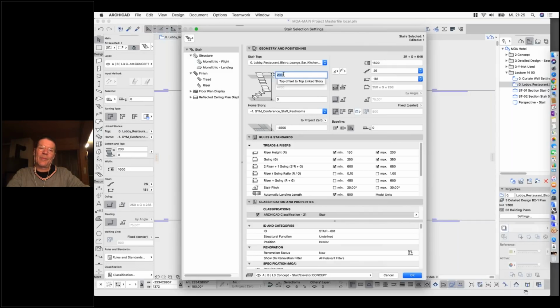top. The second important thing, beside of course the width of the stair, is the setup of the first start. Either you can start with a riser or the tread, and you also can end up with a riser or a tread. So I decided to have at first a riser. This is visible on the tiny sketcher, and I want to end with a tread.